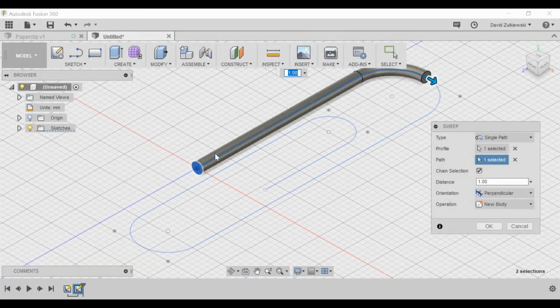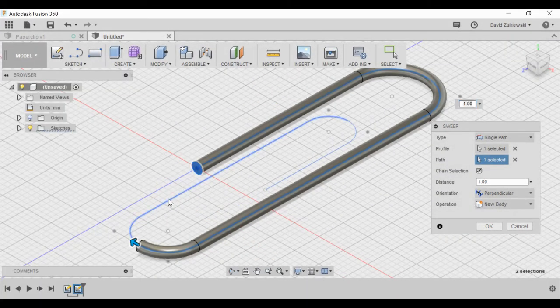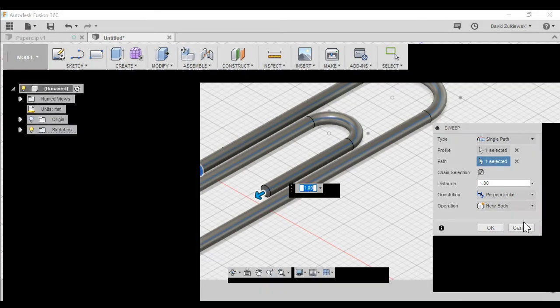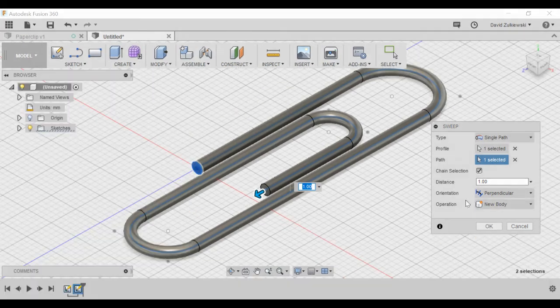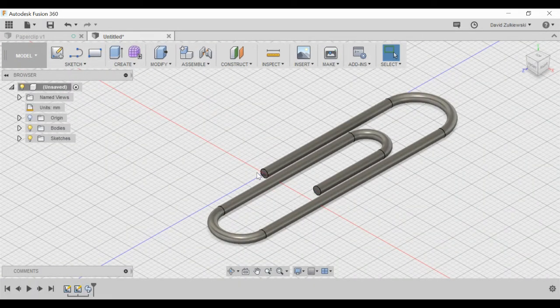And now if I click on this, it'll generate just a little piece, but I want to keep going. So if I click on the next one, and the next one, and the next one. Again, different operating systems, different versions of SketchUp. You might have to hold down Shift or Control while you go around and click those, or you just click each individual segment and it will work. Okay, pretty basic idea, but did a lot of neat stuff here.